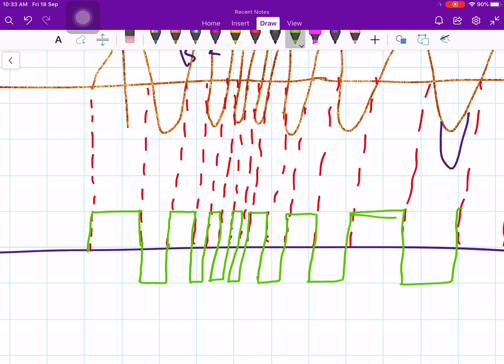So we are basically converting a smooth sinusoidal signal into a square wave kind of frequency modulated signal. Again, here also see the period is not the same. Here it is highly compressed and here it is sparsely located. So instead of modulating your message signal by a sinusoidal carrier, you are modulating the message signal by a square wave carrier.